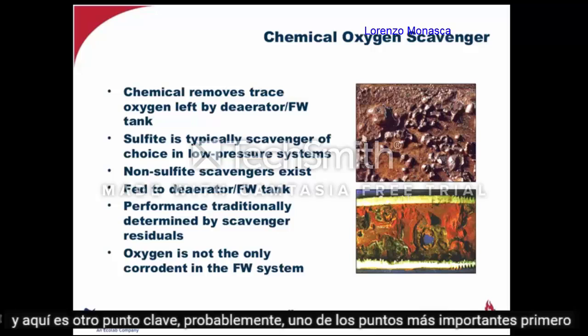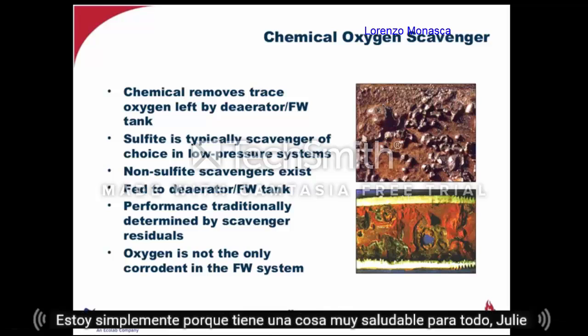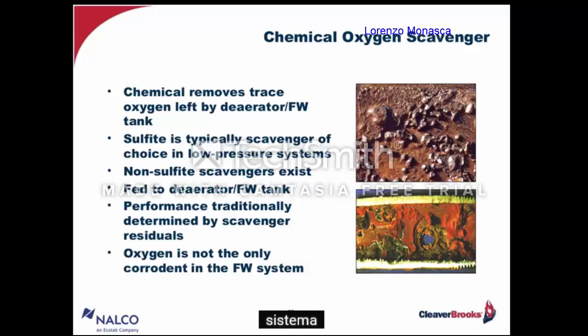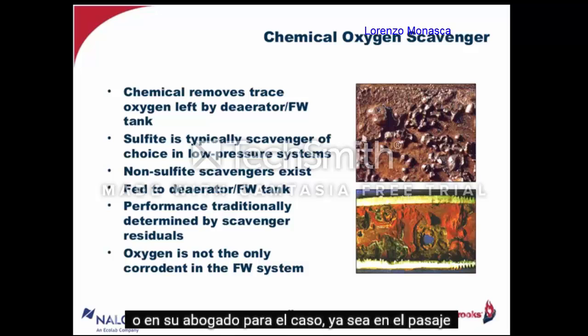And here's another key point, probably one of the most important points that I personally am going to make today. Just because you have a very healthy sulfite residual in your boiler doesn't mean that you've scavenged all the oxygen in your feed water system or in your boiler for that matter either. Oxygen and scavenger can exist very nicely side by side. It's very much a time and temperature thing.